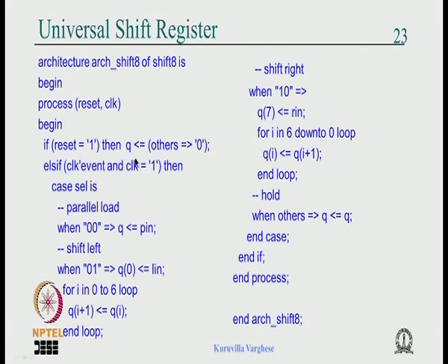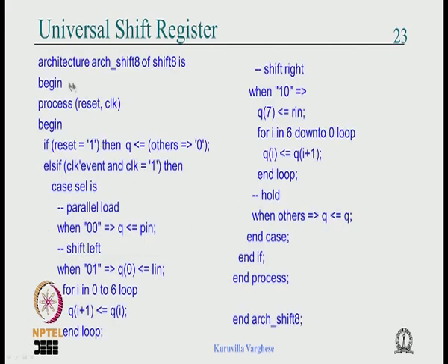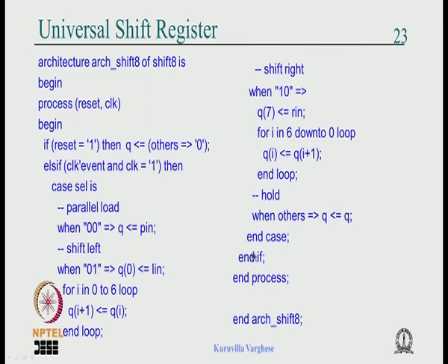So we have to assign a signal, and we have to declare a signal called Q here, which I have not done, but we can do that. Instead of a port here we will declare a signal. Imagine that this has some other name and we have a signal Q here, because Q is going on the right hand side, which is not the right thing to do. So we have to declare this a signal. Sorry for the minor error, but assume that the Q is a signal here.